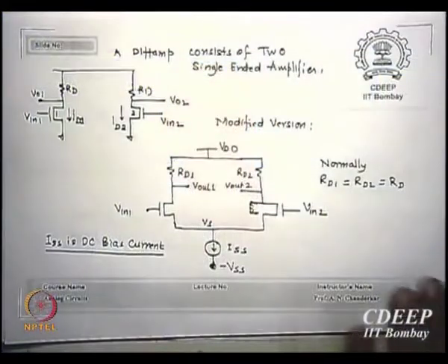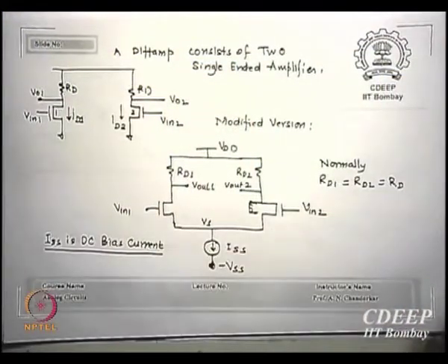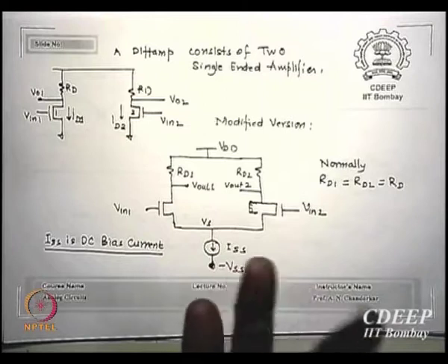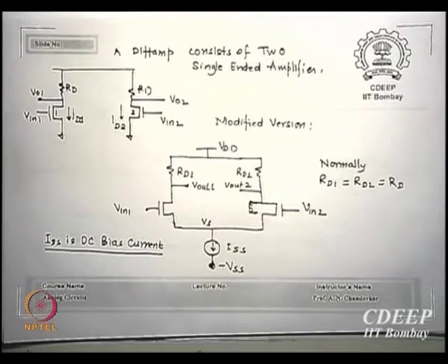And then the gain I am looking at is V in 1 plus V in 2 by 2, and if the noise is the same, what is the common mode value? It will be the same as the noise, and the output will become 0. That's what I am going to say. So noise will get eliminated at the output.